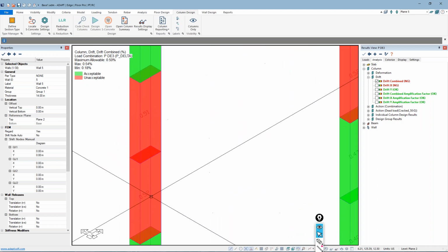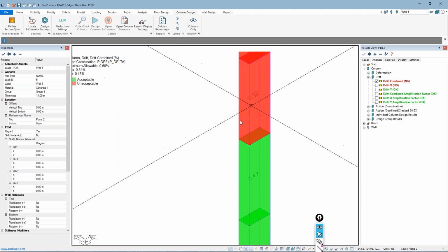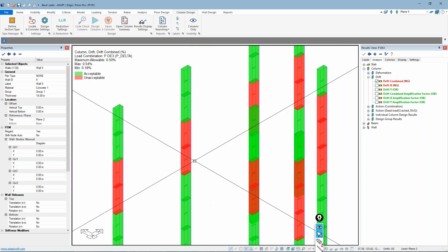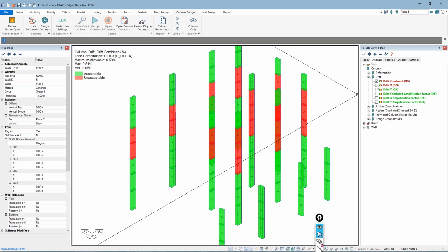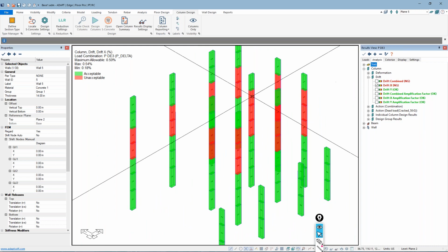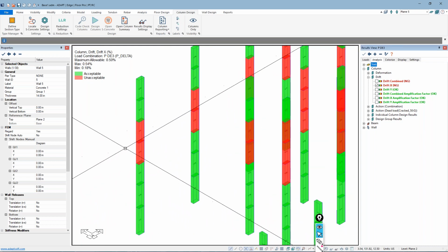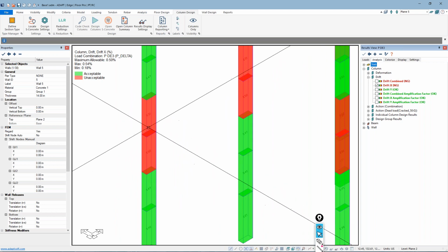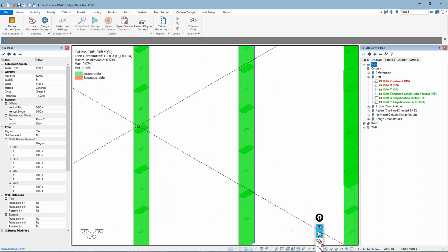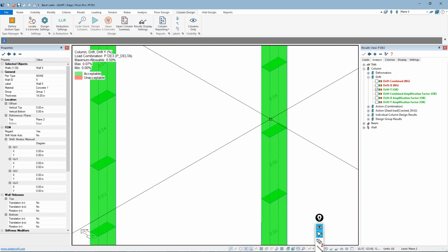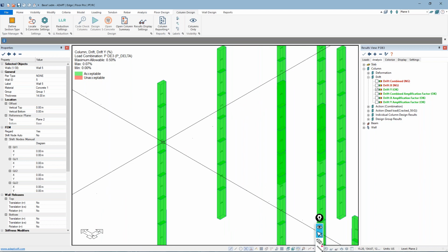And if we look at some of these values specifically for this combination, we can pull out exactly where we exceed that number. I could go into drift X. This again includes EQX. We would expect that that's driving this number here. Or I could go to Y separately. In the Y direction, under this particular combination, the drift is quite small. So there's nothing going on there.